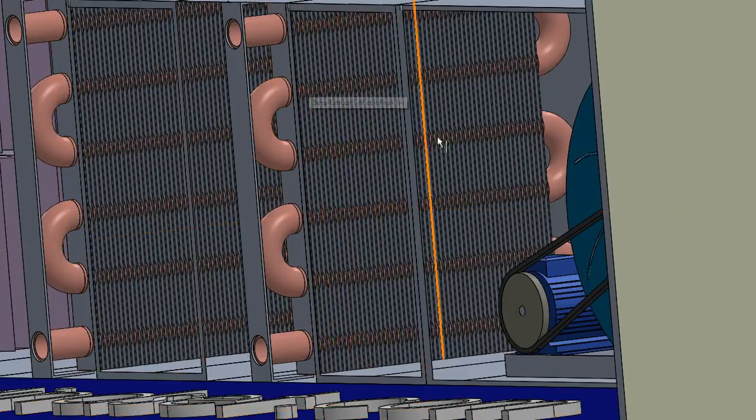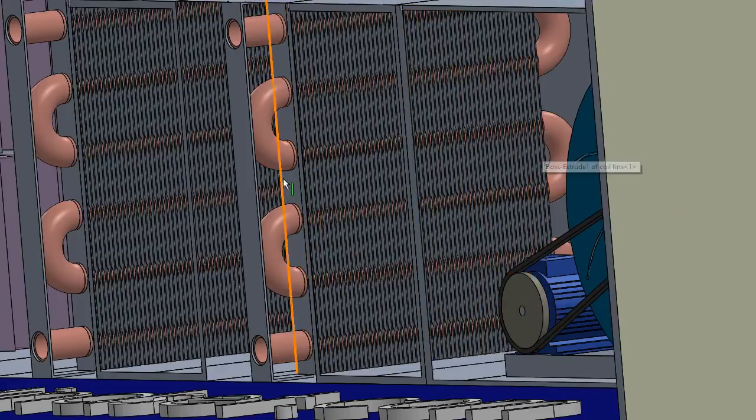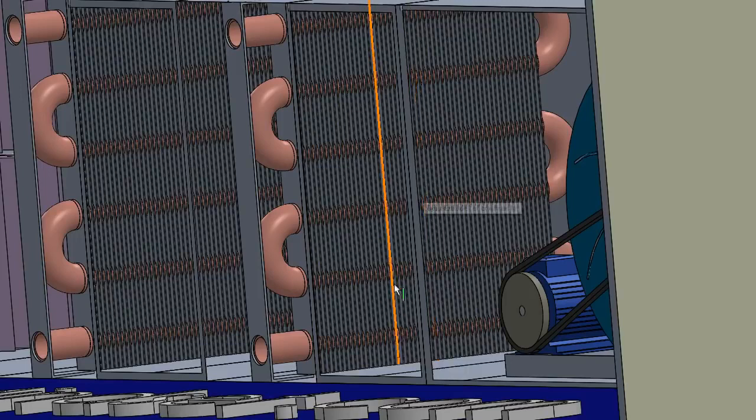And between there are all these fins. Now these fins are usually something like aluminium, and they're incredibly thin. They really are very fine sheets of metal. Very delicate as well. If you knock them, it will dent them and it will damage them. You can get some combs to bring those out as well.